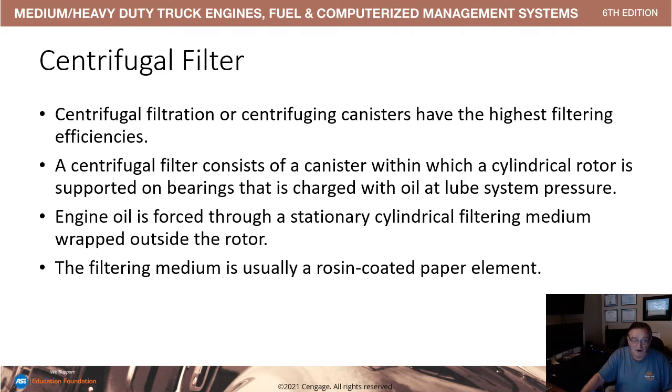Centrifugal filters or centrifugal canisters have the highest filtering efficiency. They consist of a canister with a cylindrical rotor that is supported on bearings charged with oil lubrication. Engine oil is forced through a stationary cylindrical filtering medium, and the filtering medium is a rosin-coated paper element.